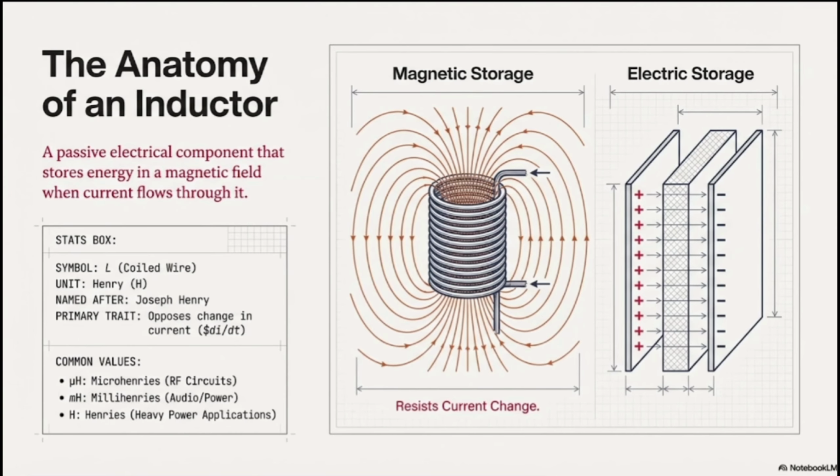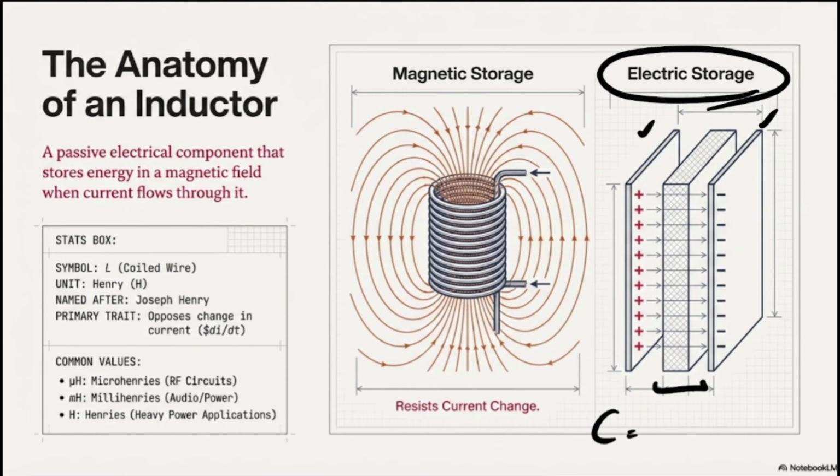If you remember when we were talking about the capacitor, we had two plates, the first plate and the second plate, and those plates were in parallel. In the meantime, we had another core between them. Why did we have that core? Because based on the formula, C equals K epsilon A divided by D, by putting a core rather than air, we can increase the capacity of our capacitor. It means that we can store more charge inside the capacitor itself.